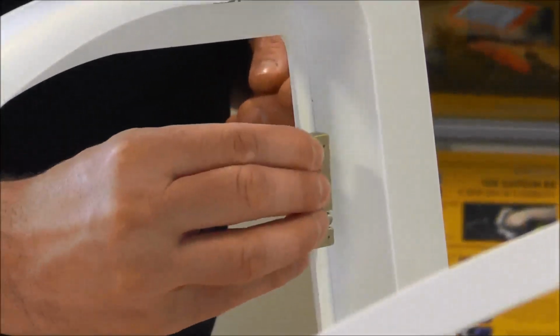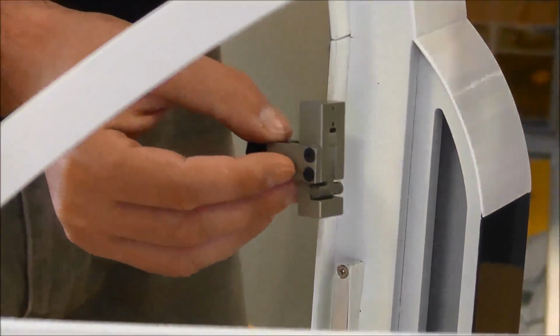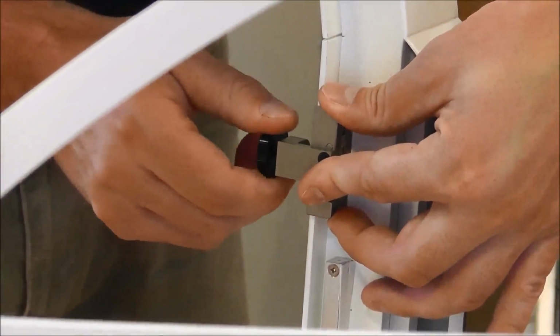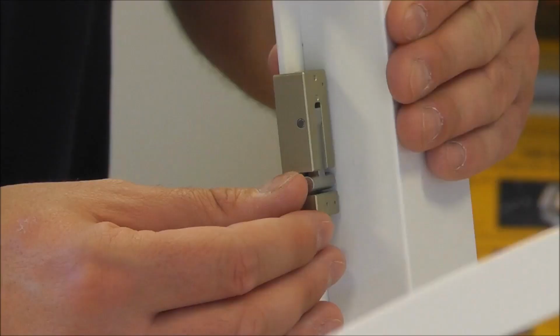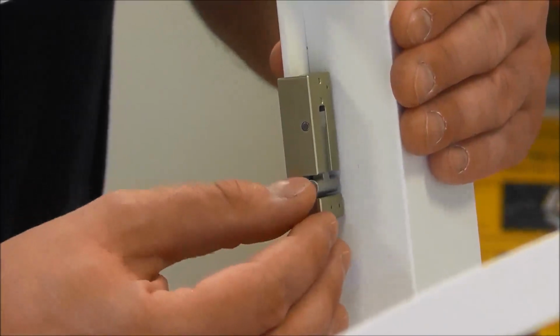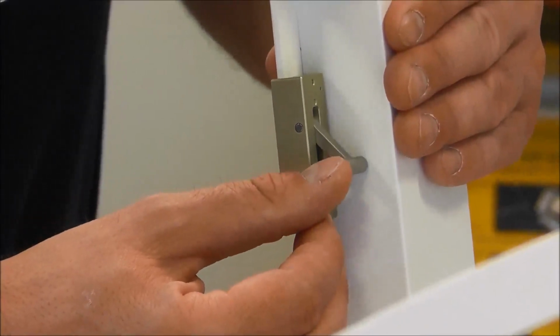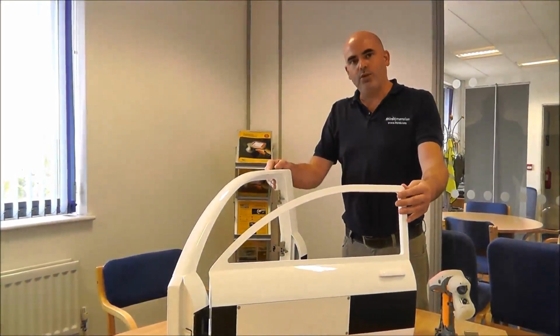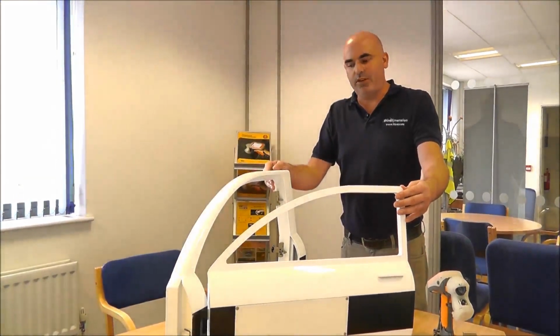First of all, we're going to attach the seal blocks to the door. For magnetic blocks, we simply snap onto position on the door frame. For screw fit blocks, we simply push them against the frame and screw until tight. Now that the blocks are in position, I pull the plunger to its maximum position on each of them. Now we close the door, which will push the plungers on the block into position.